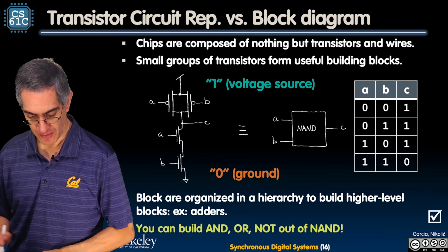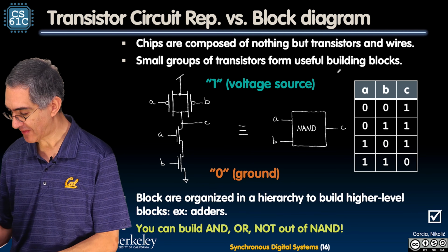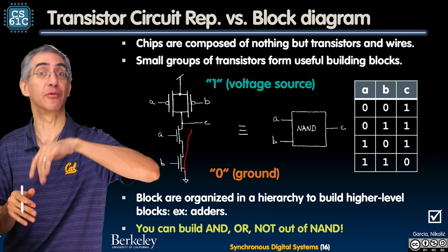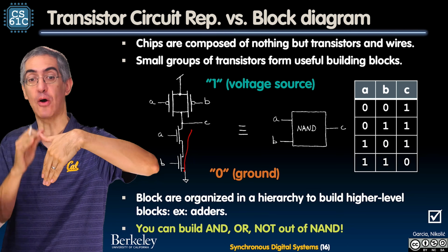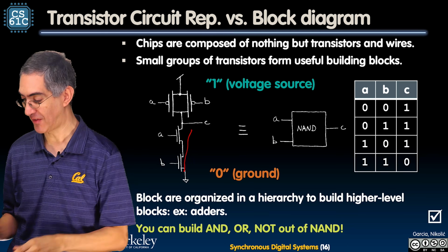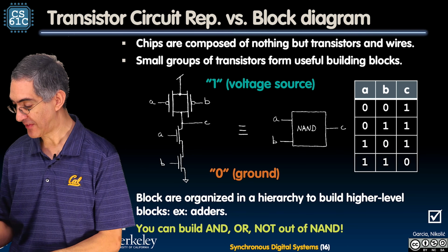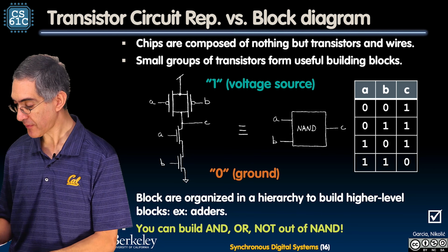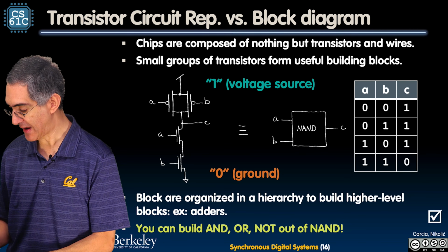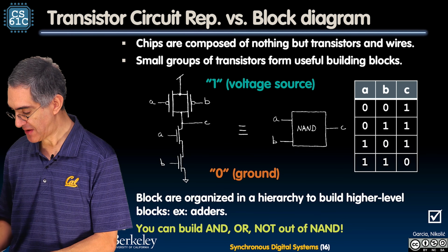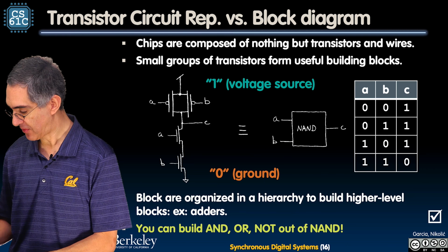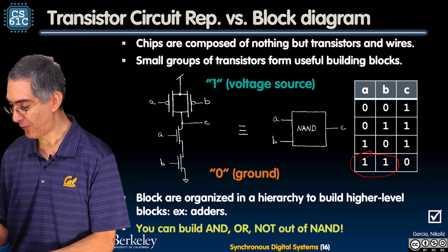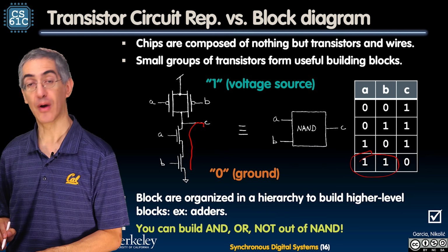So this is a serial line, two switches in serial, we said that. And in fact, C only connects when A and B are both high. These are both N-type. These are P-types up here. So when A and B go high, that's over here. Only when A and B go high, only then is C connected to ground.